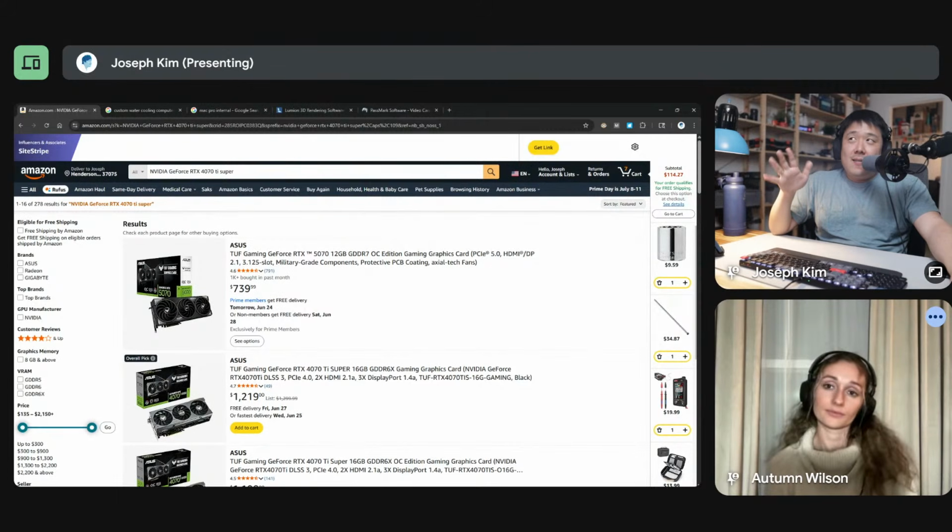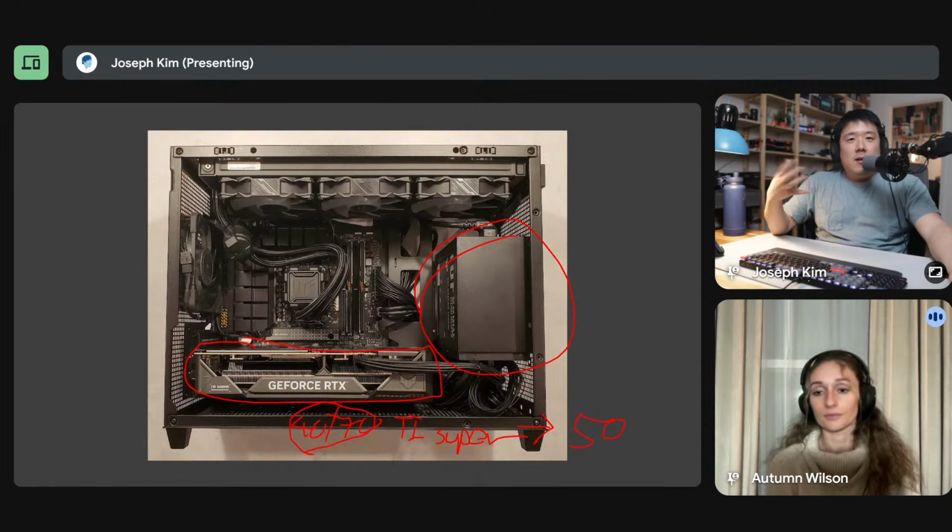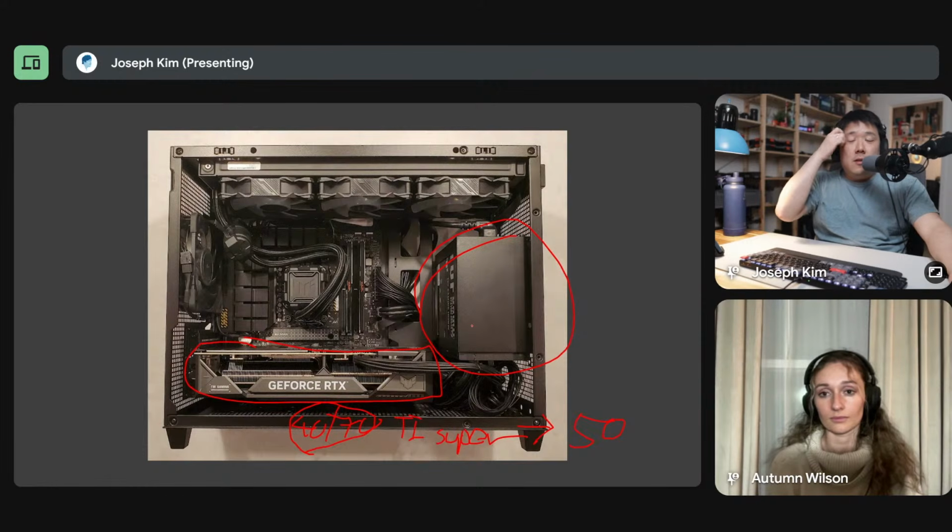Yes, there is a bit of a requirement. When you had a 1060, for example, the itty bitty older card, it's not going to have as much power draw as this card. This is going to draw a lot more power, therefore you need a better power supply. But again, you can replace your power supply from, say, 300-400 watts to 600, 700, or 800 like this one.